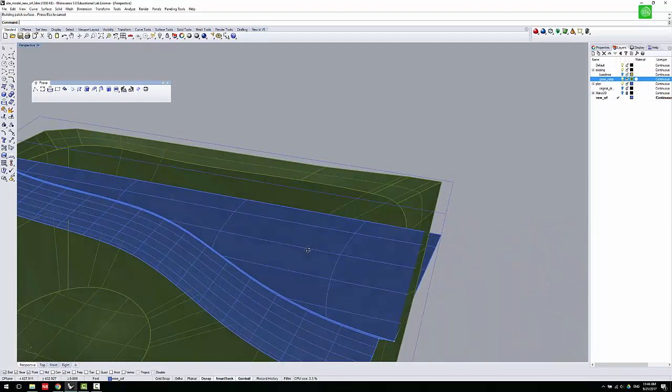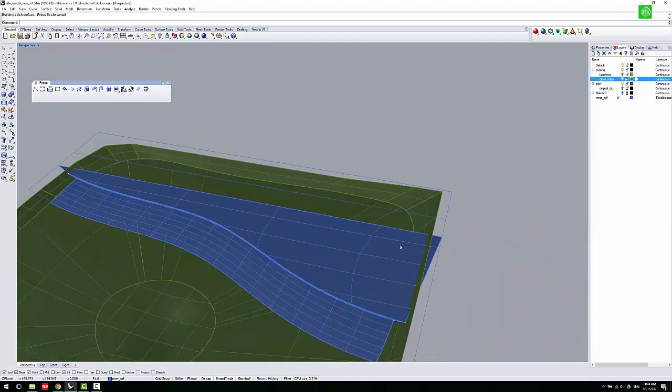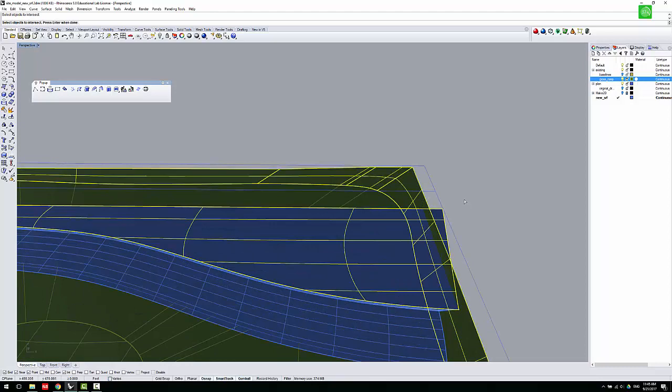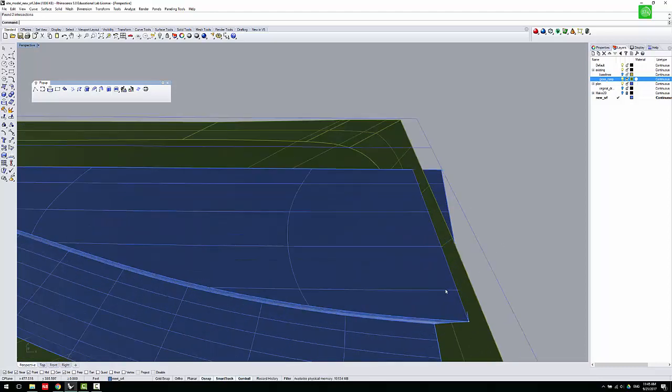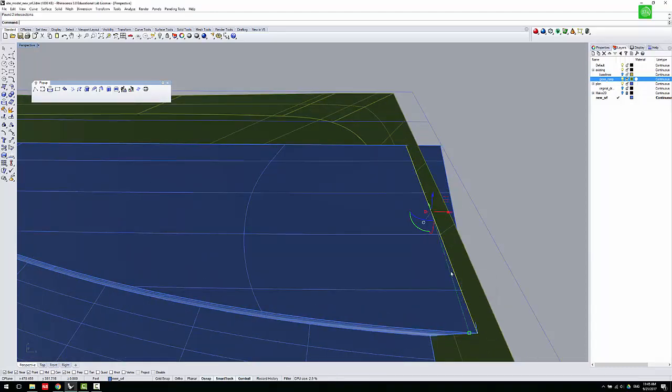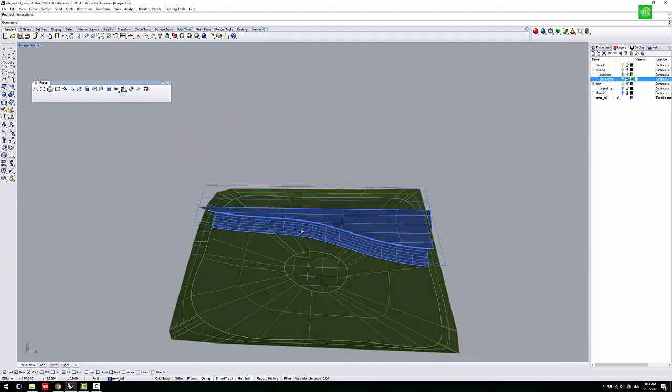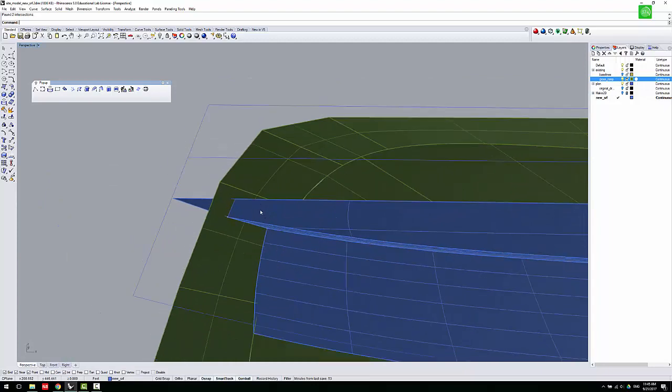But you see here the face outside. How do you do that? You can use intersection. You can intersect them again. So intersect, and this time we intersect the face. Once you intersect the face, you'll get the curve. That's the difference. You use a curve to intersect a surface, you get points. But if you use surface intersect surface, you get a curve.